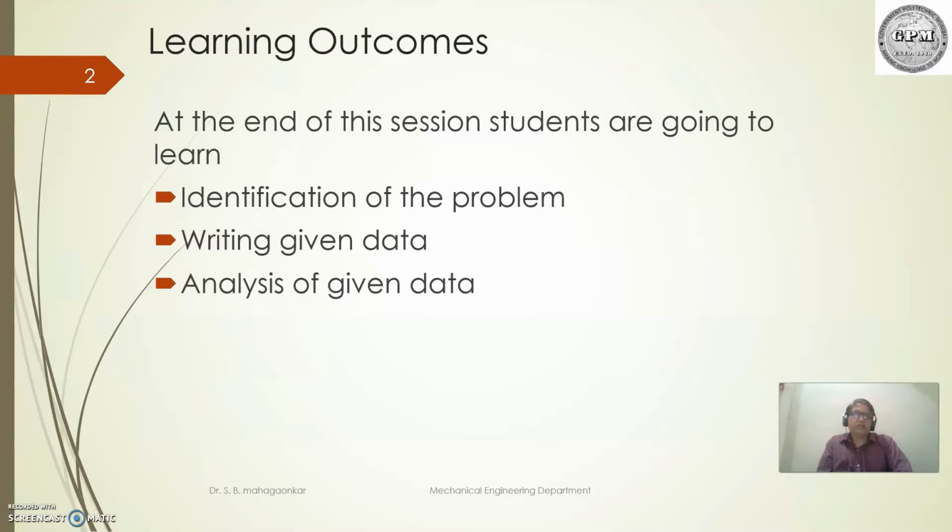They calculate the torque in Newton meter, and then use the stress value in Newton per mm square, so the answers are in neither meters nor millimeters. So you have to always check the stress units properly.